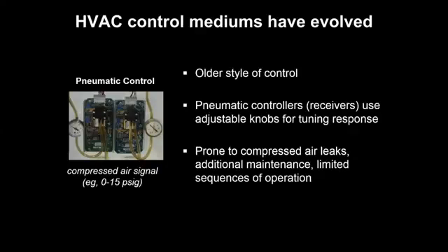But it is subject to a lot of extra maintenance with the compressed air systems, with the air dryers associated at the discharge of that compressed air, and then you gotta constantly maintain or have some type of leak detection program in your system, as that will not only use more energy to keep cycling those air compressors, but will start affecting your ability to maintain your sequences of operation.